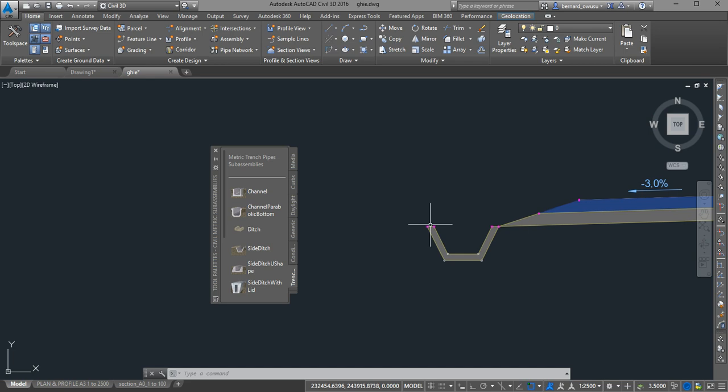Okay, whatever. But you may have, let's say, your backfill, you may have a side slope. You may want to slope it, either if it's in a cut or if it's in a fill. If it's in a cut, then you have a slope this way. If it's in a fill, this will be down there because it's in a fill. It will not be collecting something from down to top. So we are going to put what we call the daylight.